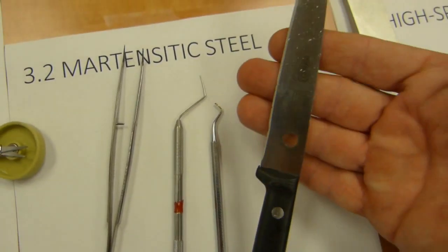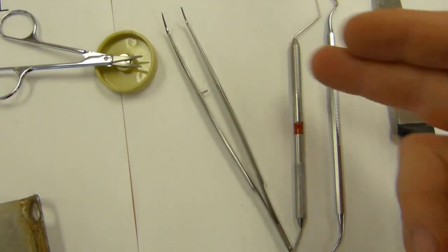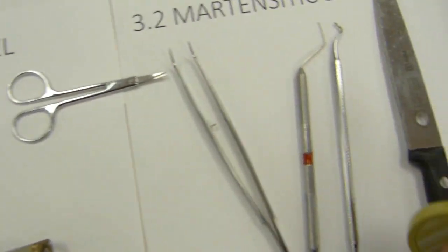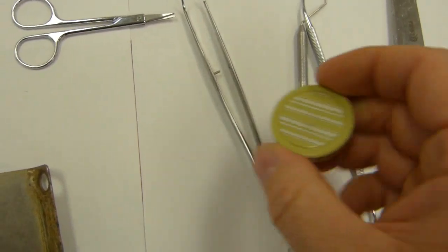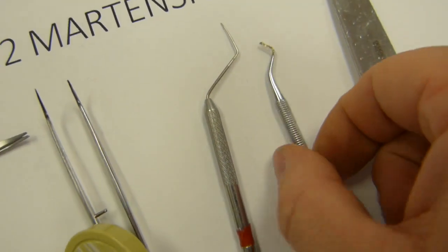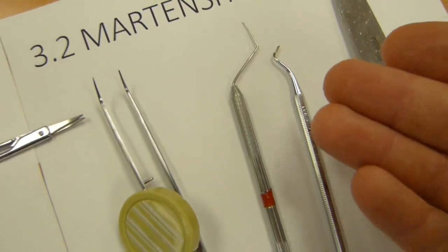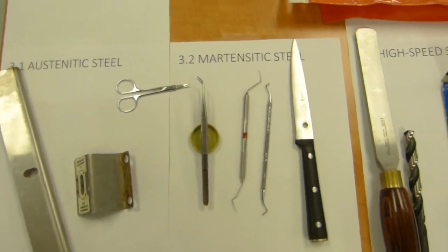Chef's knives that you can keep on a magnetic strip on the kitchen wall, where they should be dried instead of thrown into a drawer. And of course I have tweezers and dentistry tools. All of this is magnetic. They also rust, not right away. They are stainless, so they stain less than usual, but they are strongly magnetic, all of them, with a loud clunk. You can see some rusting there on dental explorers, which are for removing scale, the calcium deposit, from the teeth. This tweezers is also rusty somewhere, there at the tip, where we have just enough good light. The dentist throws it away after a while. And that's the end of the story on these Martensitic stainless steels.